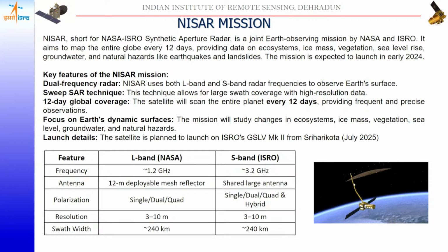But if we want to increase the swath, then we have to compromise with the resolution, because we use multiple beams. Those multiple beams utilize the synthetic aperture time which is used for the synthetic aperture creation. That reduces the synthetic aperture length and the resolution in the azimuth direction. So ScanSAR increases the swath but reduces the resolution. But this problem is solved using the SweepSAR mode, which has both high resolution and high swath.